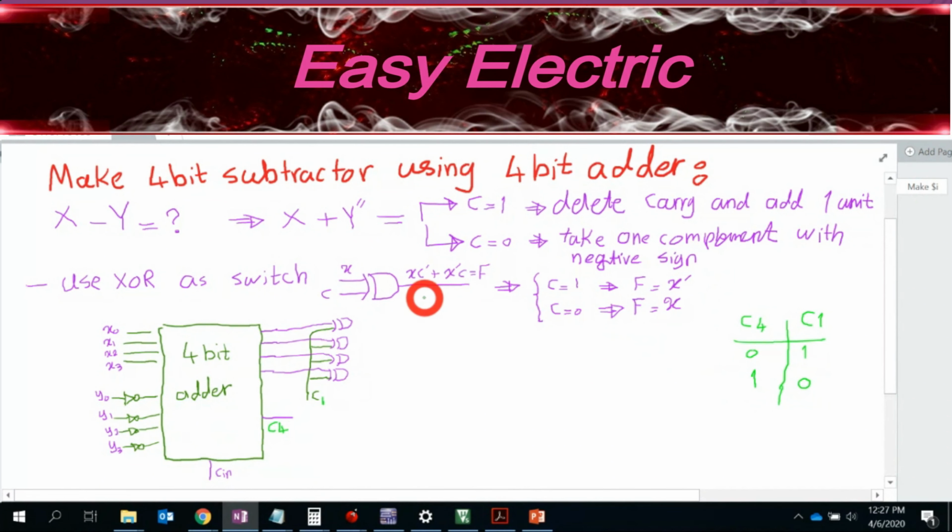Whatever you have as S, it should be just passed through to the output, which is definitely whenever the control is 0, it actually passes whatever you have. So right now you want to make this function. You tell me if I make this function C1 based off C4, is it right? I say C1 equals C4 prime. The answer is right. So the C1, whenever C4 is 0, you take not, you have 1. Whenever this is 1, you take a not, it's 0.